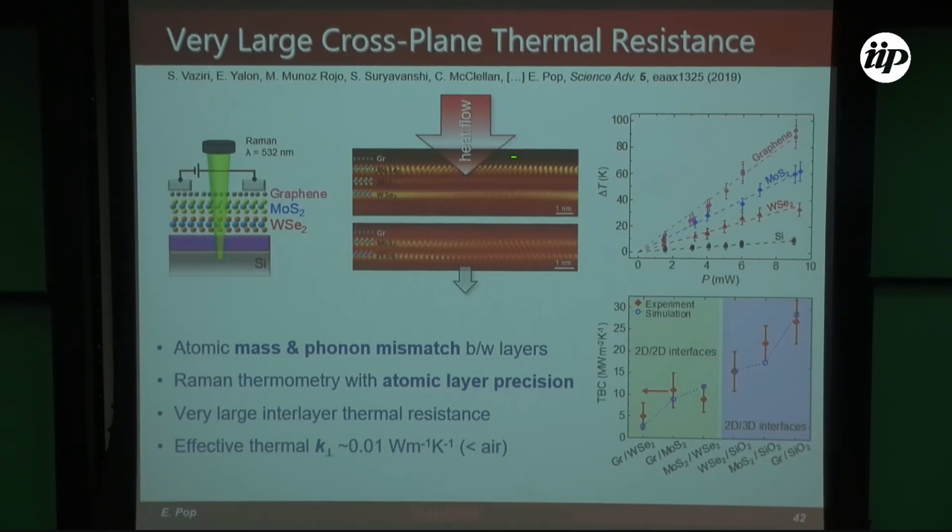Very clever guy. So he said, let's just use the graphene. See, the top layer is always graphene. Graphene's always the top layer. And we use that as the electrical heater, because the electrical heating of graphene is very well quantified. If you put 4 probes on it and you push current through it, it's fine. And then, of course, the heat will flow downwards, and then we can still measure the individual Raman modes of the individual layers. We can figure out their thermal conductivity.